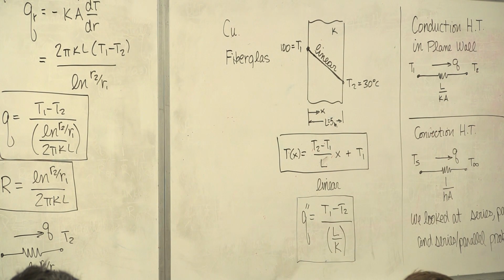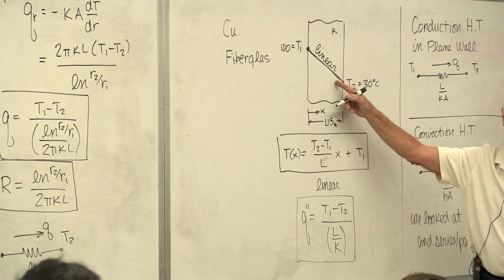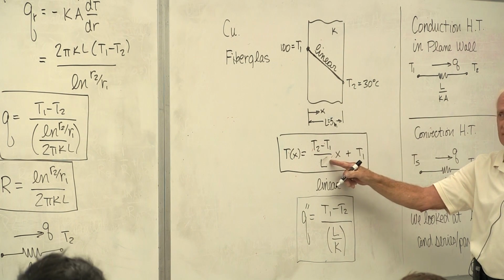Oh yeah. There's where the material comes into all this, in the heat flux. So yeah, it sometimes amazes people. They think, well, there must be a difference in the temperature profile for copper and fiberglass. The answer is, sorry, there's not. Same thing. Because in the equation, K disappeared.